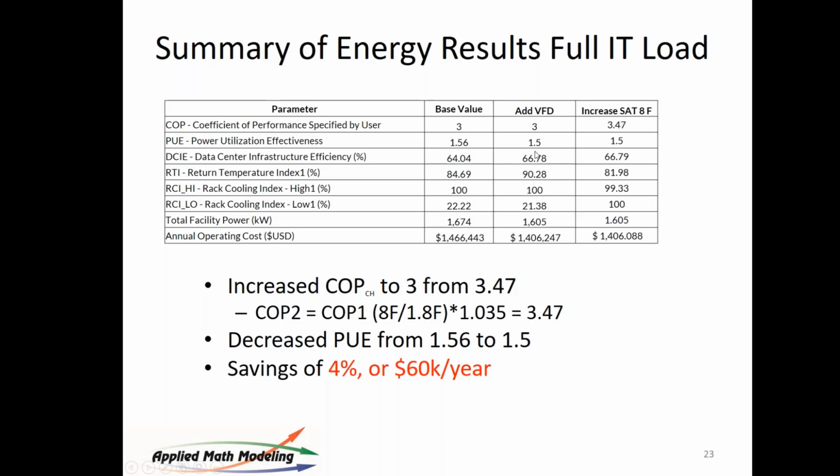That's as good as you're going to get, whether you tweak the VFDs a little more or tweak supply air temp a little more. Now, if we went to containment, we could probably get a few more degrees out of it, and the fans may slow down. But in this case, we're operating at a PUE of about 1.5. And I've seen these kind of data centers operate this way with fairly good PUEs. So that's why I wanted to point it out to you.